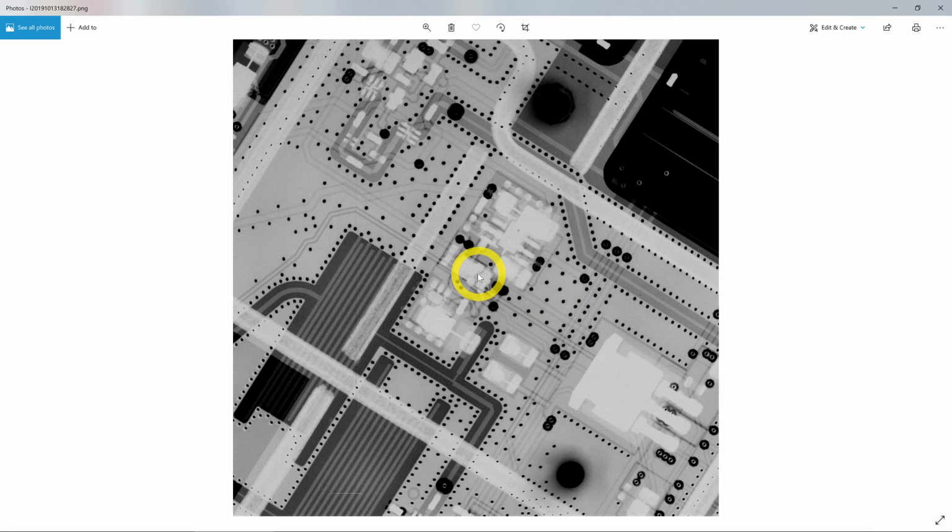So let's take a look at some X-rays that I took off the board, and they look pretty nice. As I mentioned earlier, the filters for the different bands of the LO synthesizer are buried within the PCB layers, and in the X-ray you can clearly see the filters for the different bands. It's sometimes difficult to bury these filters between ground layers because you're so close to each ground from the top and the bottom that now you have all these extra capacitances, and sometimes it's hard to meet the bandwidth, or just hard to create the characteristic impedances you want with this.